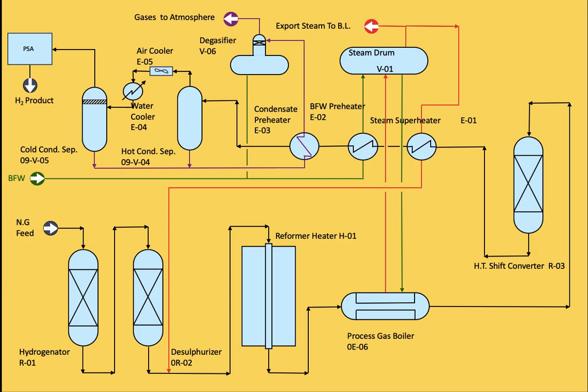So what will you do if you notice a little coking and an increase in the delta P across the tube of this reformer? The symptoms of this condition are, first, a rapid pressure drop increase across the tube. Second, loss in methane conversion. Okay, and hotspots can be found also. And catalyst deactivation and possible tube plugging. Okay, all this is related to the reformer.